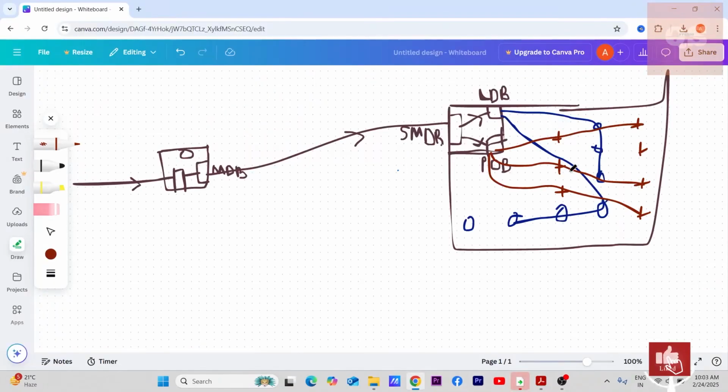All these in blue color are for the lighting circuit, and this red color is for the power circuits. These are usually in numbers, not in meters, because as per NRM2, for the final circuit, that is wiring or cabling for these fixtures, is counted in numbers. For example, you see 1 2 3 4 5 6 7 lights, so if there are 7 lights, the final circuit for lighting will be 7 numbers. Power sockets, 1 2 3 4 5 6 7, so the final circuit under the power section will be 7 numbers.